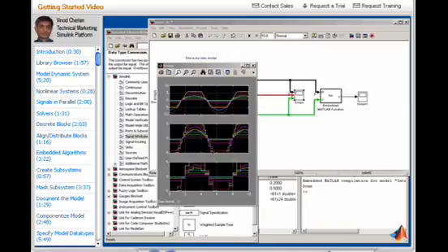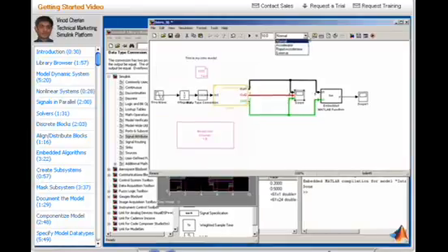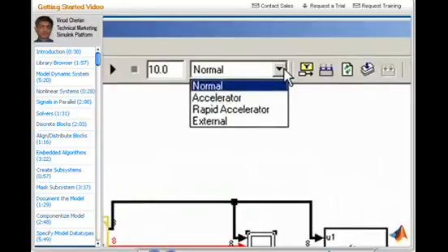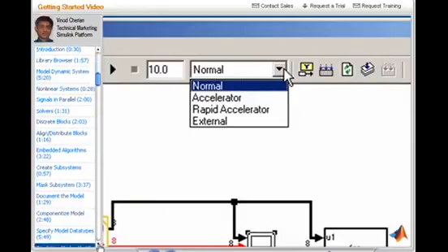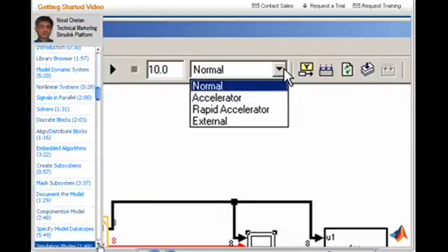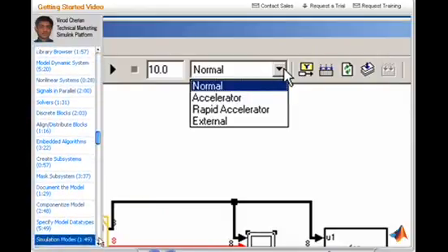Well, during design time or when building the model, you are frequently updating the model, needing to debug or inspect the behavior. At that point, the normal mode simulation is probably the best. When the model is built and you want to run it many times with different inputs or with different parameter values, you may choose one of the accelerator modes for increased simulation performance.